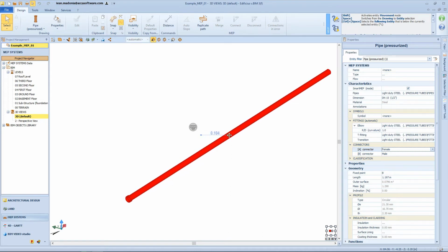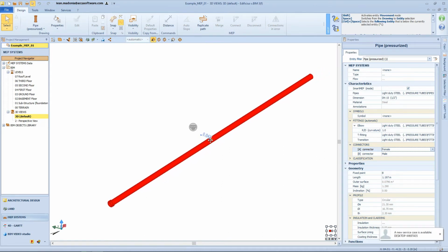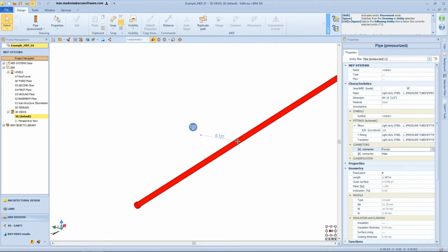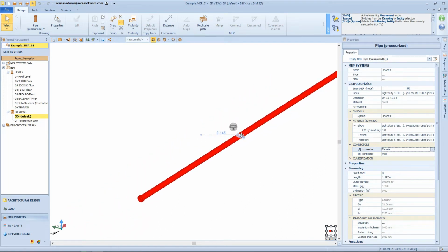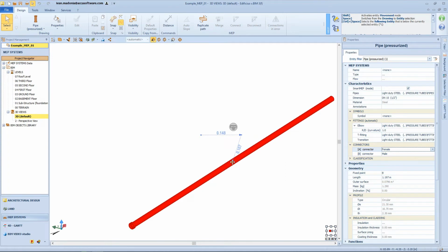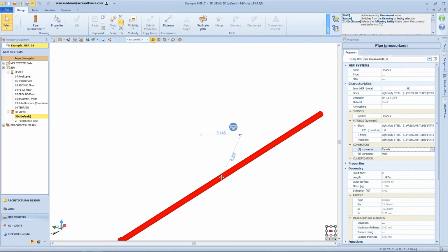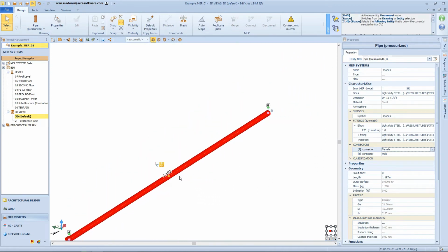By clicking on the icon with the ruler symbol or by pressing the A key from the keyboard, the measurement is activated. With a second click, a rigid segment will be represented between the initial attachment point of the anchor on the pipe and the point chosen in space, with relative numerical distance. However, the pipe will still be hooked to the mouse cursor to be repositioned, taking the chosen point as a new fixed reference. The same operation can be repeated several times to identify, for example, the distance with respect to several reference points, until the pipe is definitively fixed in the desired position.